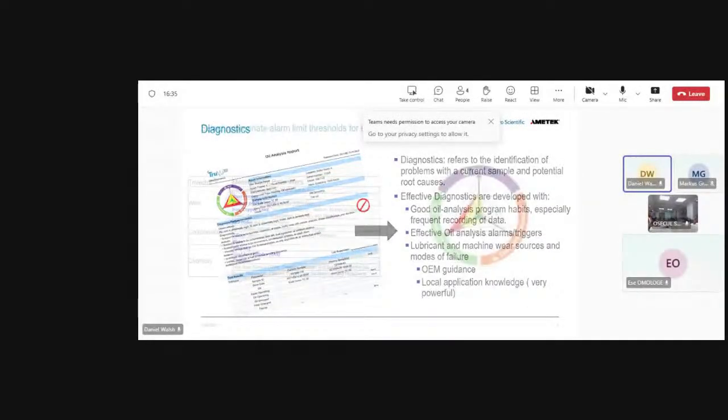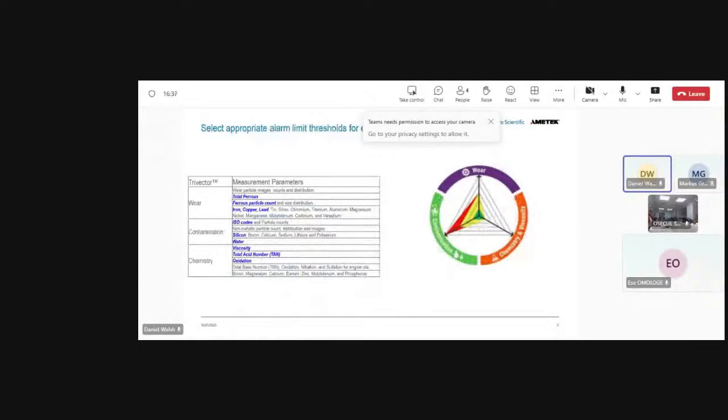What often happens nowadays is, anytime people run an oil analysis report or do an oil analysis, be it on site or off site, what you're supposed to do is make a series of tests that will identify any machine condition, which is wear debris in the oil. You want to look at contamination in the oil, water, sand and dirt, particulates. Chemistry then as well must be checked.